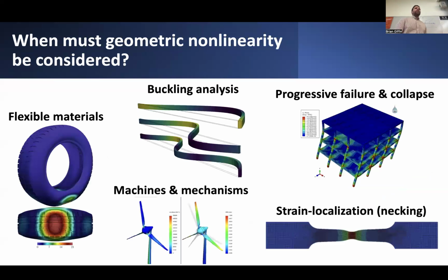Okay, now, apart from buckling analysis, when do we actually need to consider large deformations? Well, it spans a whole bunch of different scenarios in which you might want to include these features, turn them on. Certainly, buckling analysis is one. If you're trying to assess when this single member will fail in buckling, or when the whole structure will fail under some kind of unstable mode of deformation, those are things that you need to include.